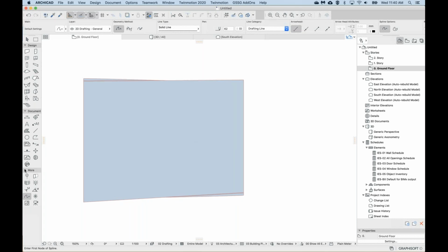Okay, great. So we're going to More and choosing the Spline tool. We're going to create a spline from about 4 points or something, kind of creating an egg shape, but it has to be contained inside this shell box that we see here.